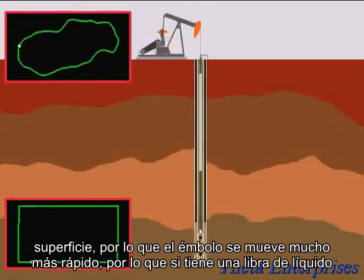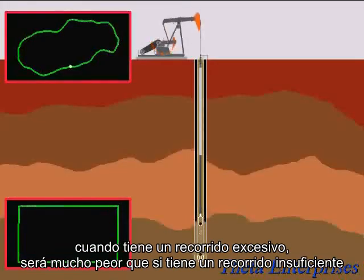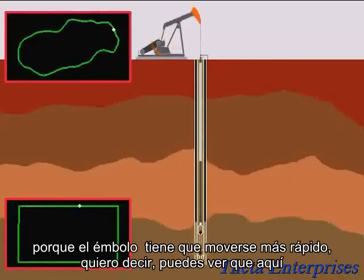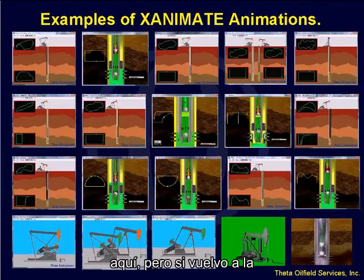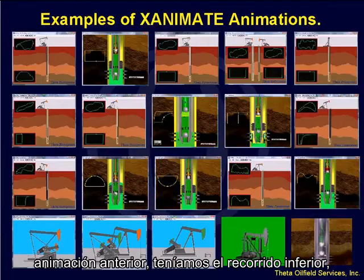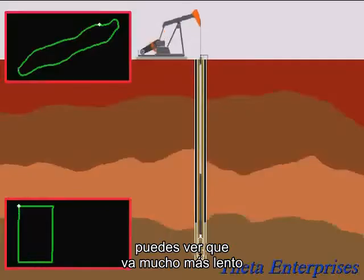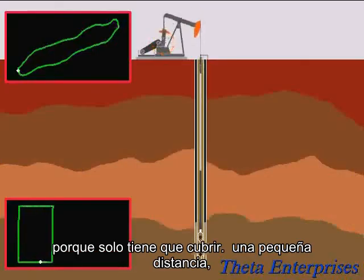So if you have fluid pound, when you have over travel, it's going to be a lot worse than if you have under travel, because the plunger has to move faster. I mean, you can see that here. You can see how fast the plunger is moving here, but if I go back to the previous animation where we had the under travel, you can see that it goes a lot slower, because it only has to cover a small distance.